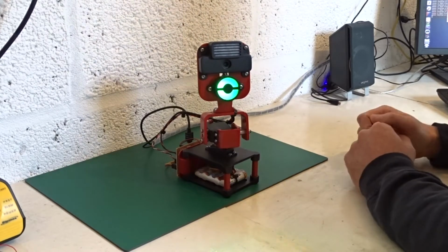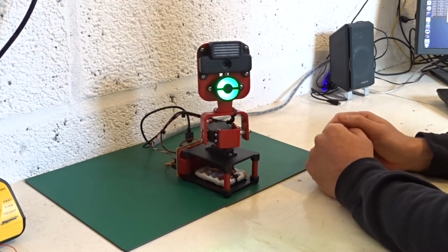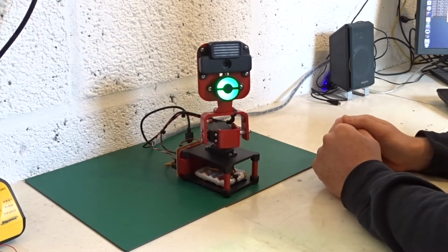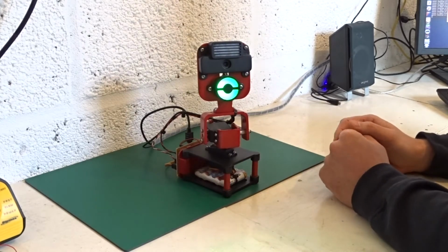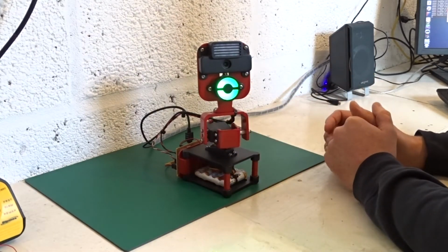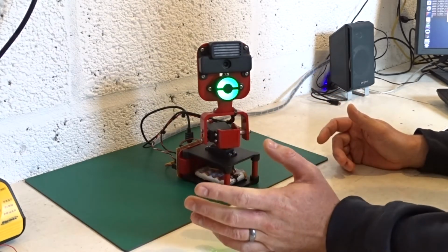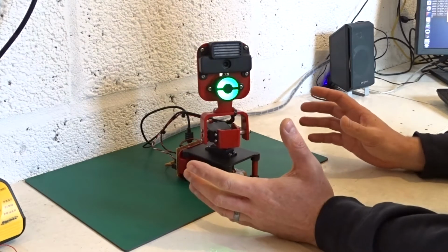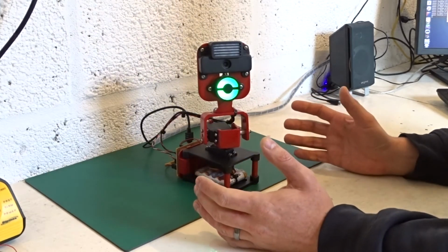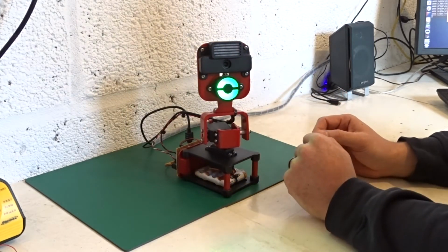And that leads me on to a slight issue with the way I'm doing things at the moment, and that is the inaccuracy of the sonar sensor. It's well known that these have a wide beam angle and are okay for detecting distances up close or in plenty of free space, but what I found from my testing is that if the robot's looking at an object a long way away, anything else in the environment nearby, be it something else on the table with the robot or me sat nearby or anything really, will really affect the sonar reading and the accuracy.